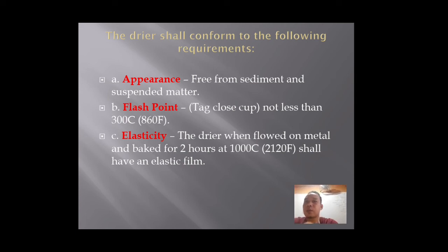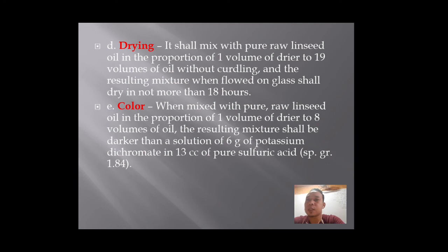have an elastic film. The next is drying, so it shall mix with pure raw linseed oil in the proportion of 1 volume of dryer to 19 volume of oil without curdling, and the resulting mixture when flowed on glass shall dry in not more than 18 hours.